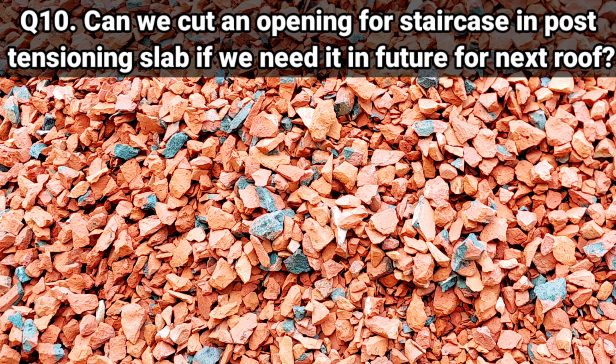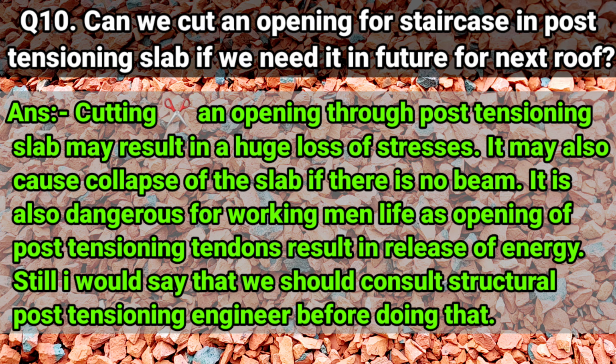Can we cut an opening for staircase in post-tensioning slab if we need it in future for next roof? Cutting and drilling through post-tensioning slab may result in a huge loss of stresses. It may also cause collapse of the slab if there is no beam. It is also dangerous for working men's lives, as cutting of post-tensioning tendons results in release of energy. Still, I would say that we should consult a structural post-tensioning engineer before doing that.